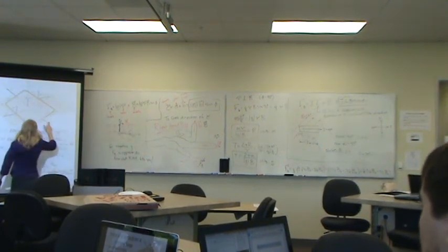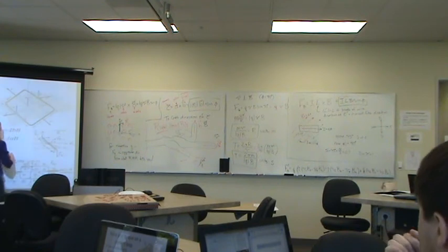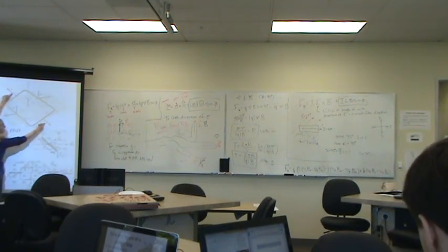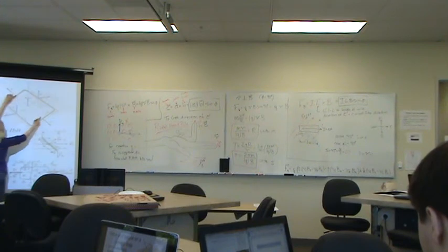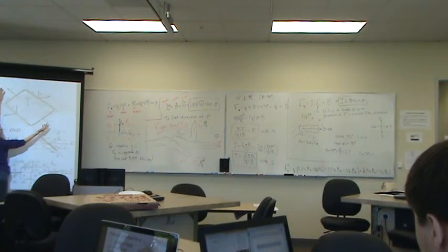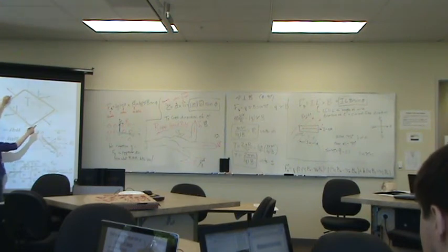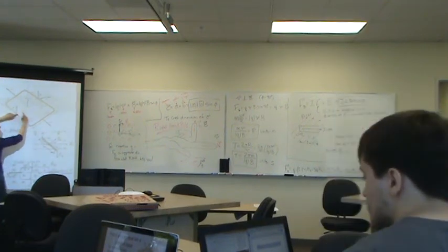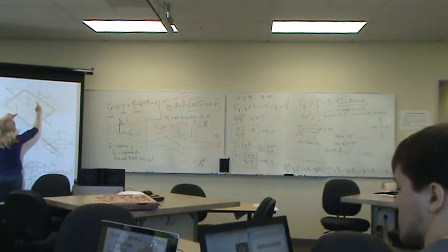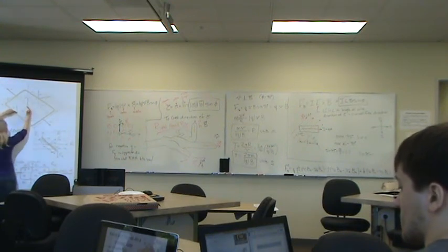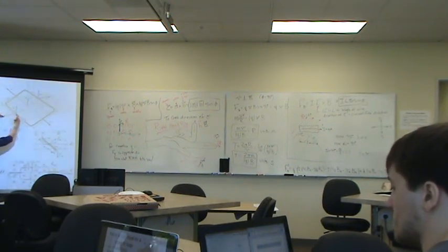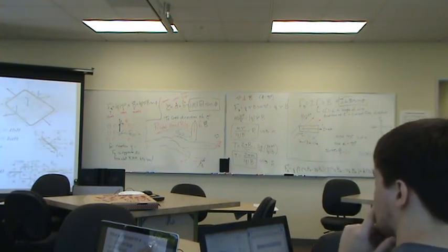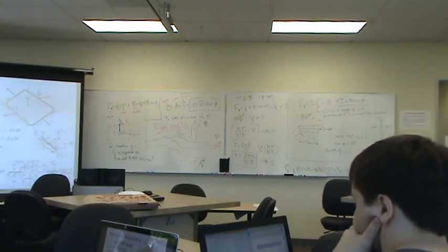So in terms of these 4 forces we talked about before, the reason that these forces along the sides don't contribute is because they're right on the axis of rotation. So the distance from the axis of rotation, R, would be 0. So the moment arm for these 2 forces is 0, so they don't create any torque. These guys are as far from the axis of rotation as you can get. And we said this whole length was equal to B. Okay, so the radius, the R value, would be B over 2 for this force and that force. And so you'd have non-zero torques, which is what causes that loop to rotate.